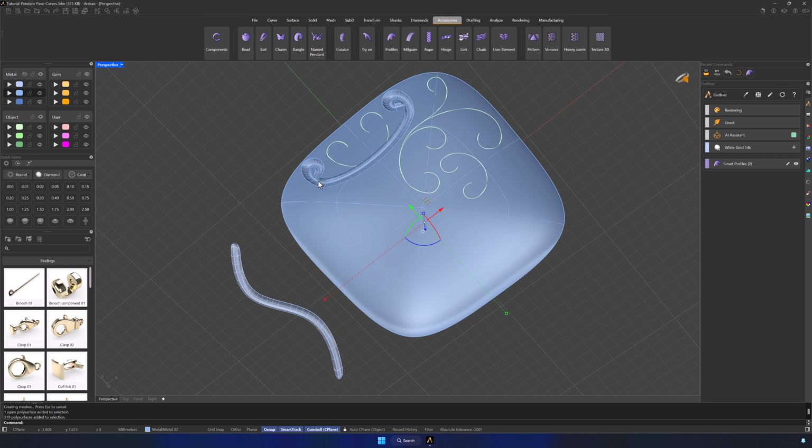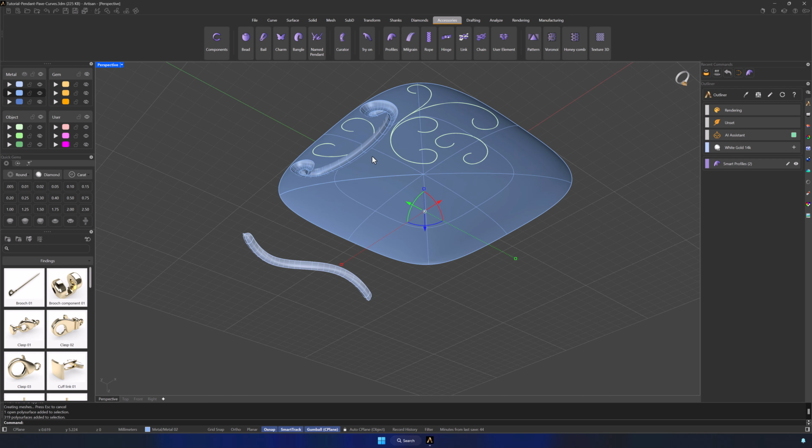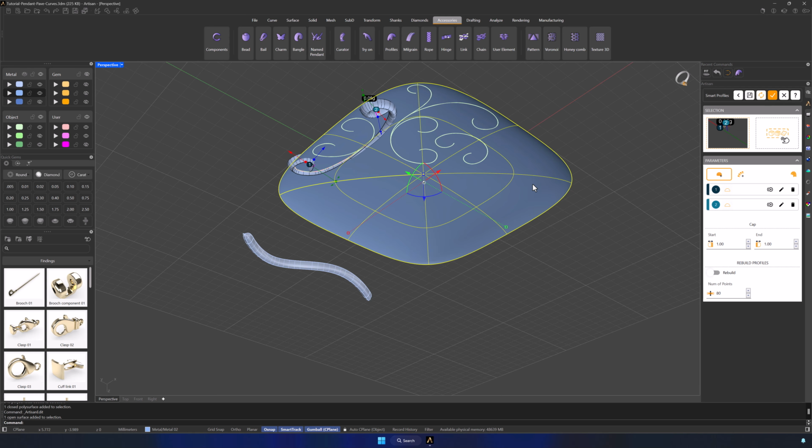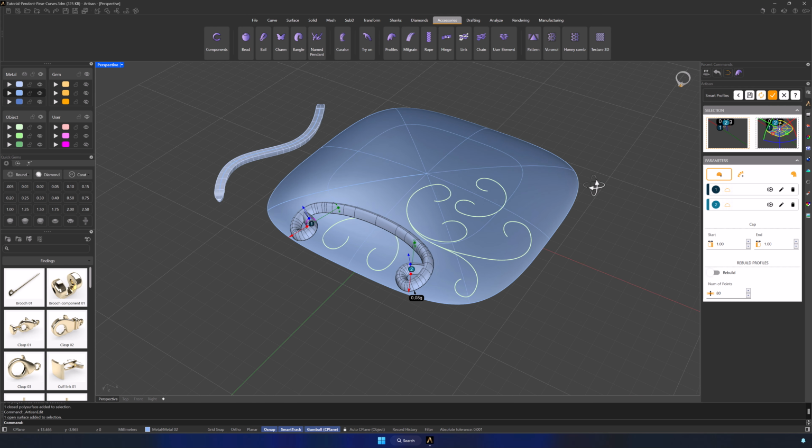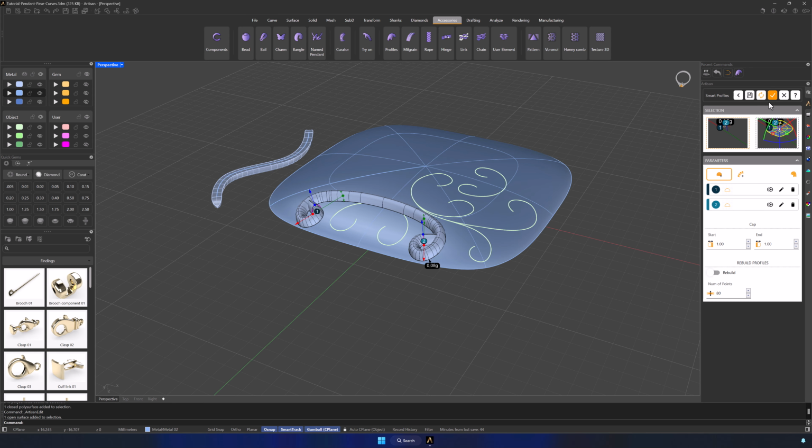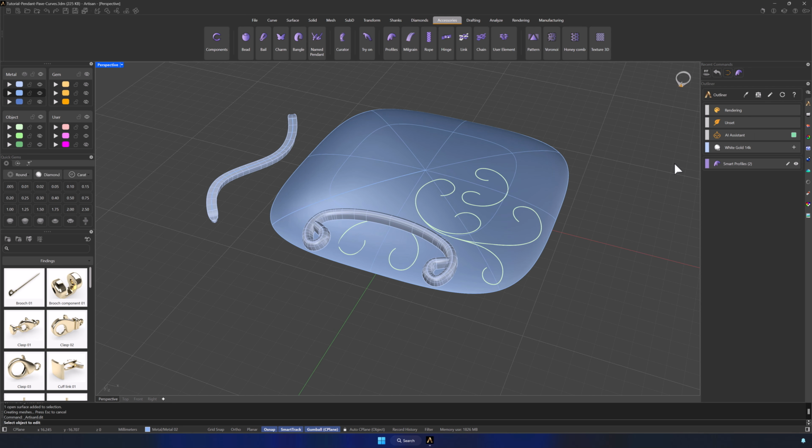Now we can see that the profile applied to the curve is positioned on the inner side of the surface. We'll edit it and assign the surface as a reference in the command selector. Now it adapts perfectly. Apply the profile to the rest of the curves. Now use the Apply Style command again, select the clone profile and apply it to the rest of the curves. To update them, select them all and click Edit. They'll automatically align to the surface.